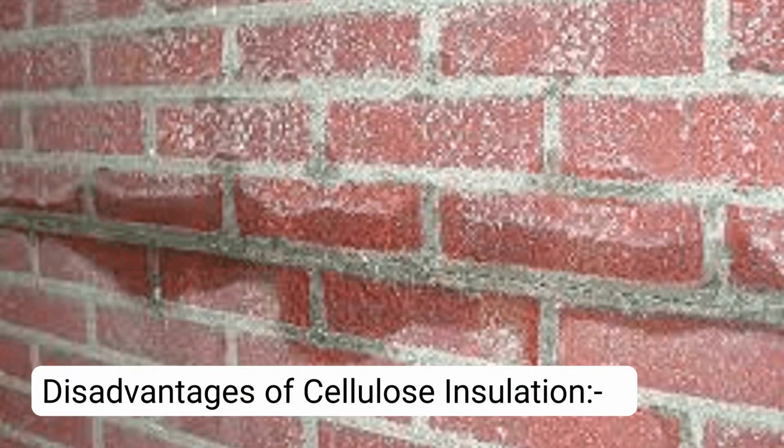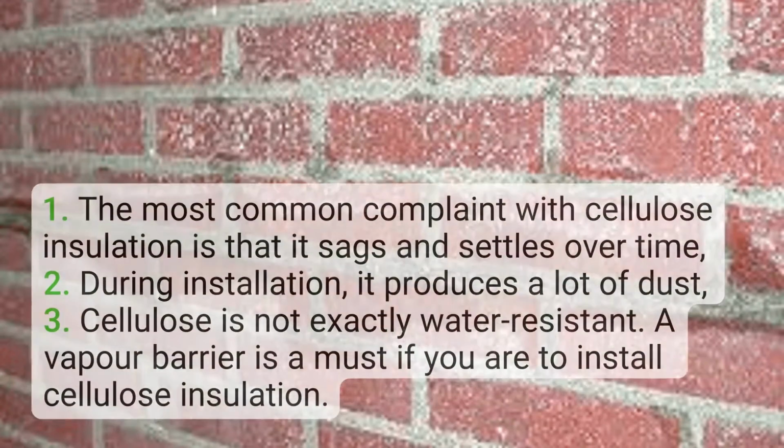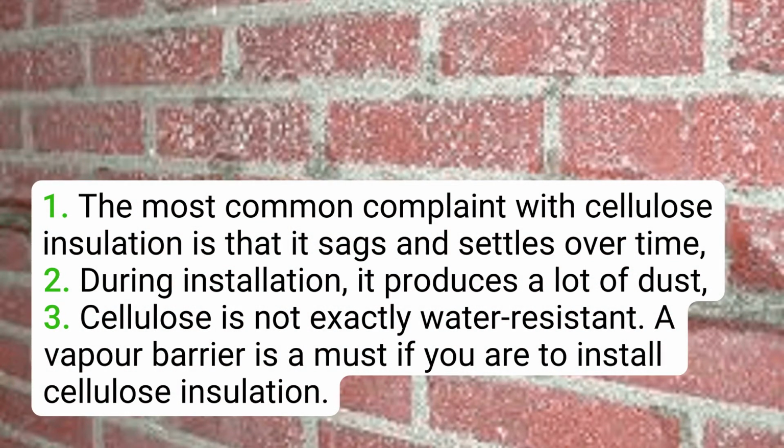Disadvantages of cellulose insulation. 1. The most common complaint with cellulose insulation is that it sags and settles over time. 2. During installation, it produces a lot of dust. 3. Cellulose is not exactly water resistant. A vapor barrier is a must if you are to install cellulose insulation.